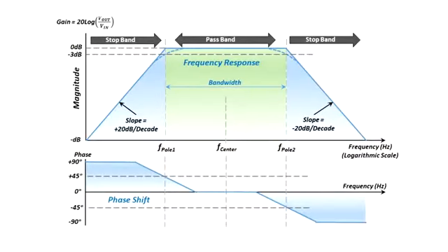As you can see in the graphic on your screen now, which is a Bode plot of a bandpass filter, the magnitude of gain is plotted logarithmically on the vertical axis versus logarithmic frequency on the horizontal axis. But phase is plotted linearly in units of degrees on the vertical axis.